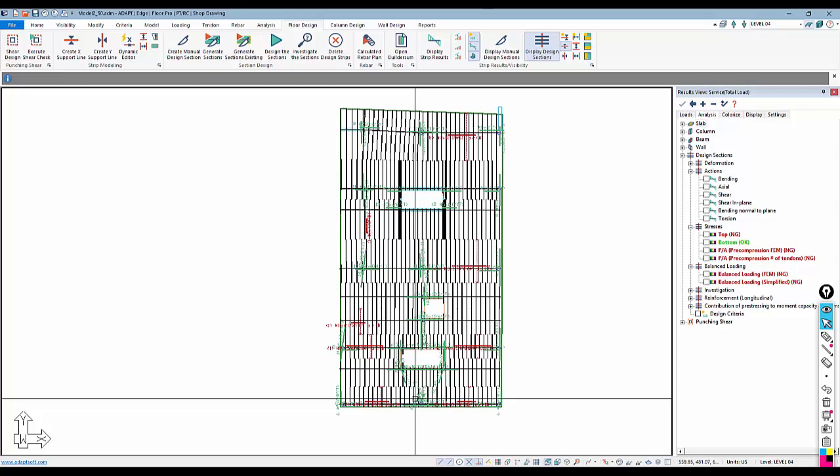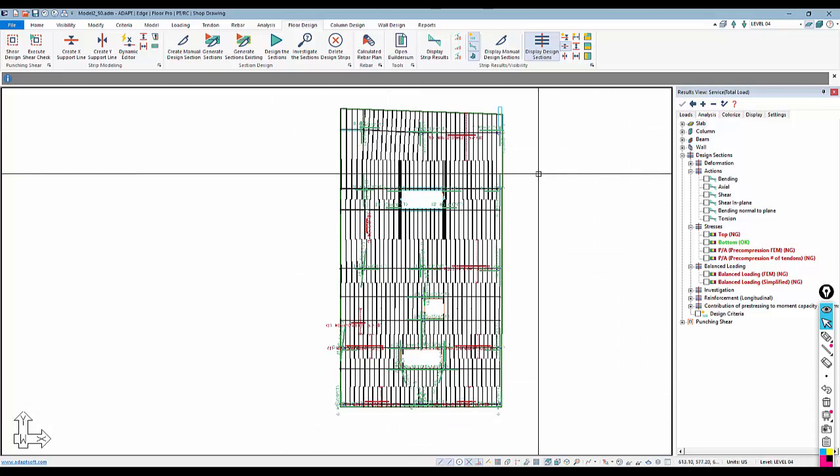Again, we're assuming that the post-tensioning is the right profile, the right force or number of cables, and the right placement for the design of both service requirements and strength requirements. And this ultimately becomes the layout of reinforcement, non-pre-stressed reinforcement, in addition to the post-tensioning.